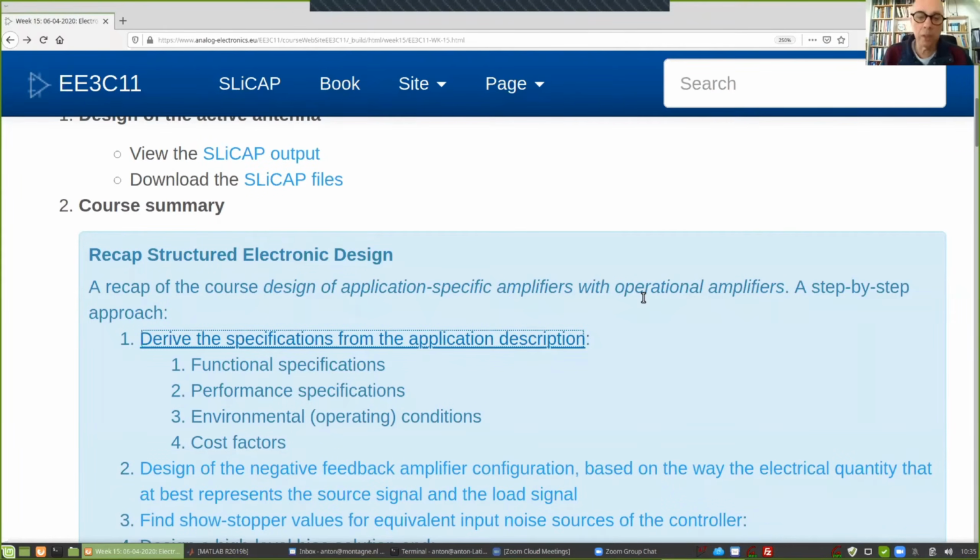And we have seen that since the impedance of the antenna is just a linear capacitor over a wide frequency range, and there is no uncertainty at all about its value, it does not add any uncertainty to the information if we take the short circuit current of the antenna rather than the open circuit voltage.